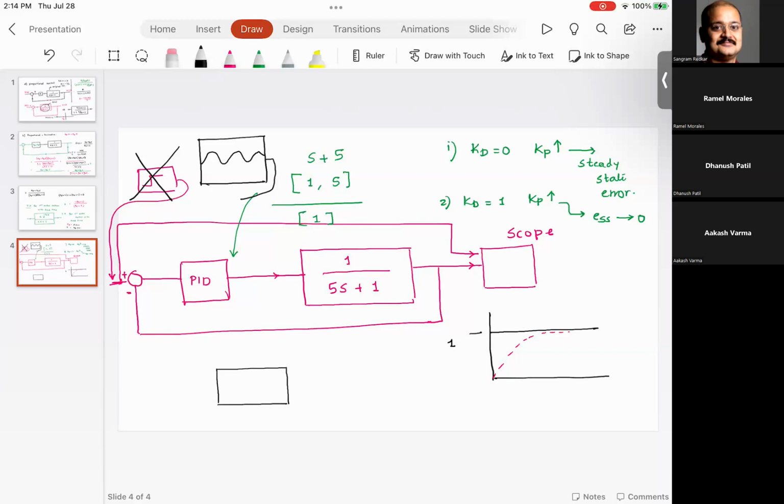There should be a delay block. No, not that. This is the delay in zero. Here we are not looking at that delay. We can use the transport delay and add that to the input. Click on the transport delay. It should ask you to change the time. Change the time delay to 5 seconds.